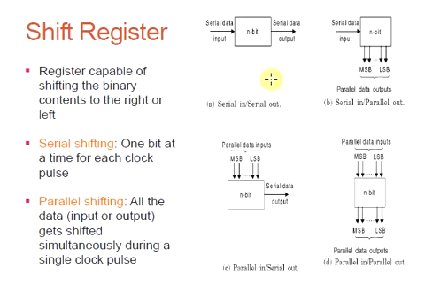So this is called serial in, serial out, and there is another one called serial in, parallel out. The second type of register is called serial in, parallel out, where the data will be input into the register as a single bit of information, whereas the output is taken all at a time. So we can take all the output information at a time. That is called the serial input, parallel output. The first one is called SISO and the second one is called SIPO.